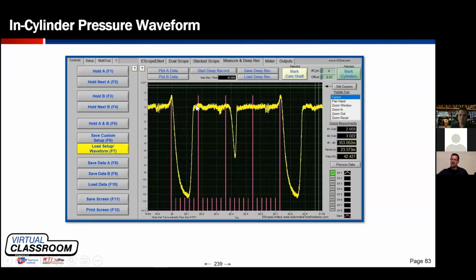This would be our exhaust stroke here, right? Very little pressure because we're cranking the engine over. And right here, the 360 mark is where the piston starts to come down and the intake valve should open up. So if the intake valve should open up, should I be pulling vacuum in my cylinder as my piston descends, if the intake valve is open? Very little, right? My piston should be inhaling. There shouldn't be any restriction. So if I got any vacuum in there, it should be cranking vacuum, maybe 1 or 2 inches of mercury. That's a fair number, right, Brent?